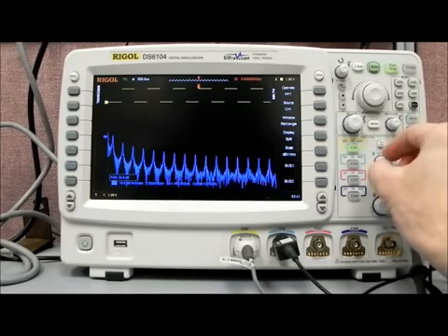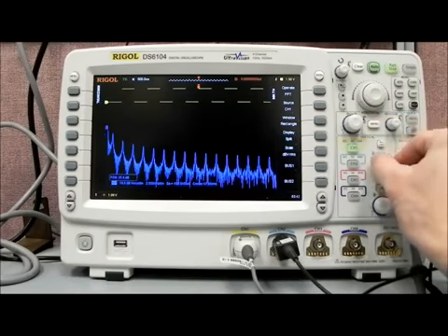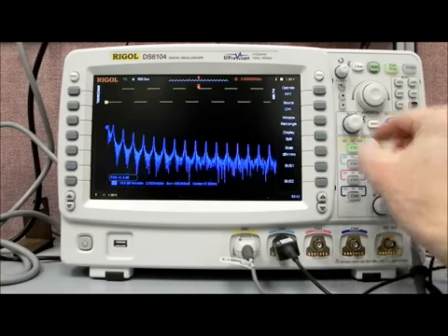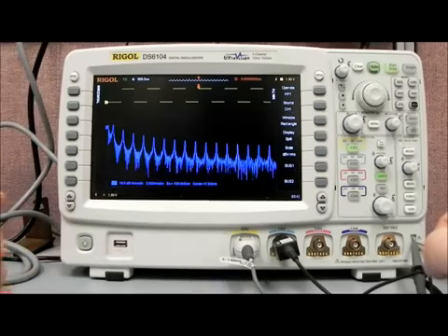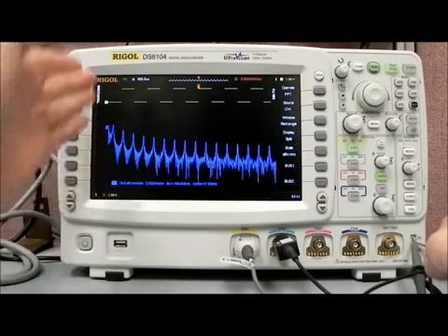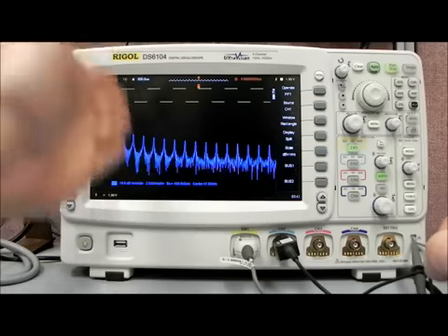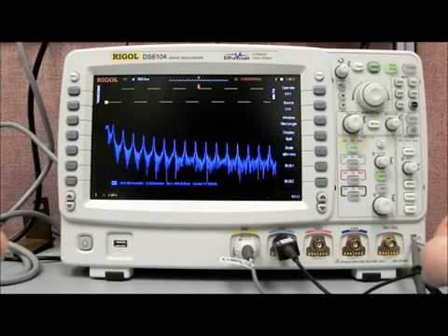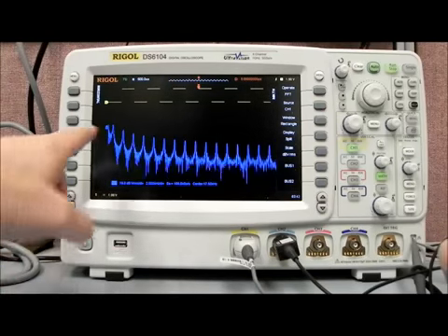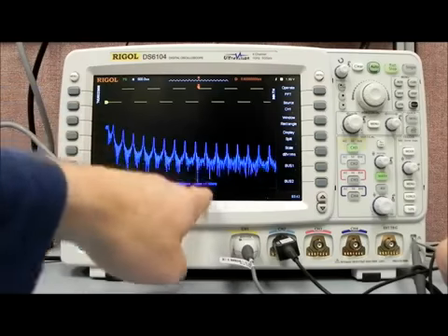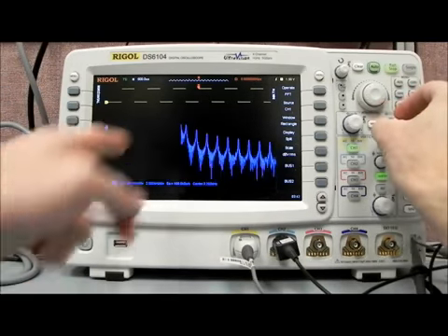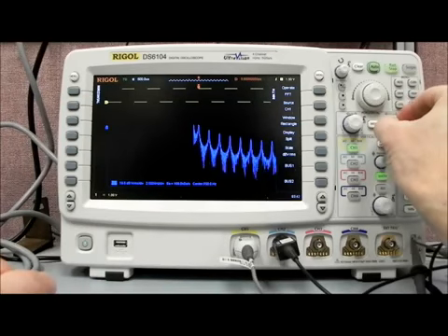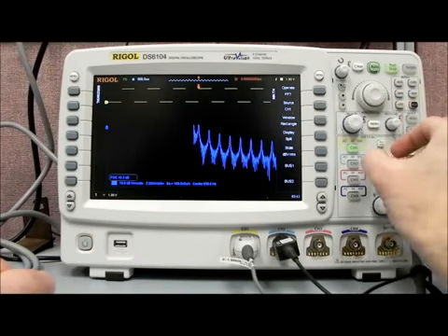But I'm just going to move the vertical position of the math function down here. And you'll see that we have a number of peaks available to us. If you remember back to your FFT, for a square wave, you're going to have a primary or a fundamental frequency, and then you're going to have all of the odd harmonics. And so with the DS6000, you can see we're reading off of the center frequency here. That's at 17K. What we can do is horizontally we'll move the fundamental frequency, which is our highest peak here. Move that down just a touch so we can see it all.